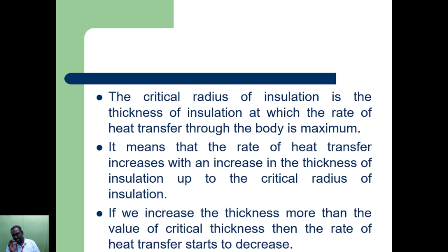The critical radius of insulation is the thickness of insulation at which the rate of heat transfer through the body is maximum. Adding the material automatically increases the heat transfer area, but up to a certain point, that is the critical radius. After adding material beyond that, the heat transfer automatically decreases. That point itself is the critical radius of insulation, at which the rate of heat transfer to the body is maximum.